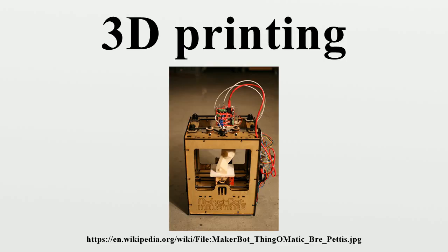FDM is somewhat restricted in the variation of shapes that may be fabricated. For example, FDM usually cannot produce stalactite-like structures, since they would be unsupported during the build. Otherwise, a thin support must be designed into the structure, which can be broken away during finishing. Fused deposition modeling is also referred to as fused filament fabrication by companies who do not hold the original patents like Stratasys does. Binding of granular materials.